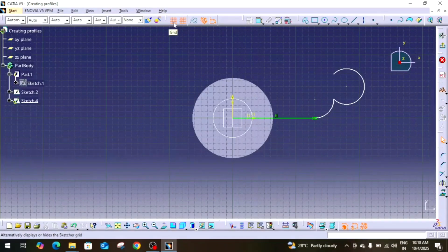By default, a grid is applied to the background of the Sketcher Workbench. This helps define the scale of sketch entities when sketching. The mouse pointer snaps to the points of the grid. This functionality can be made unavailable by temporarily deactivating the snap to point icon. This is your grid and this is your snap to point icon.